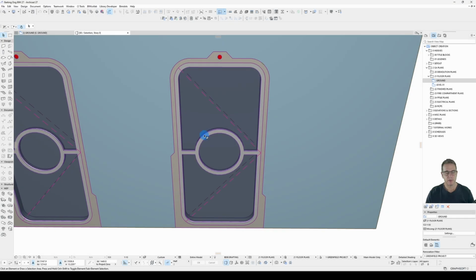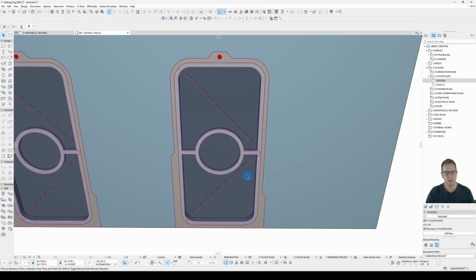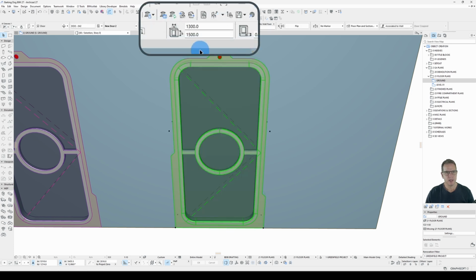With the create from floor plan method, you can't alter the geometry at all. So if I was to change this, my hotspots here, you notice that they changed. No change to my geometry. You can't change it, it's fixed. So you can change these overall sizes, but it won't have any impact on the door itself. That's why these automatically generated hotspots don't match my door geometry.